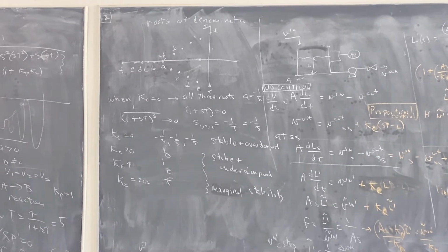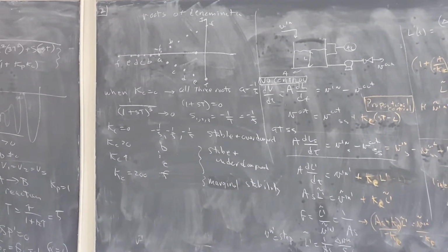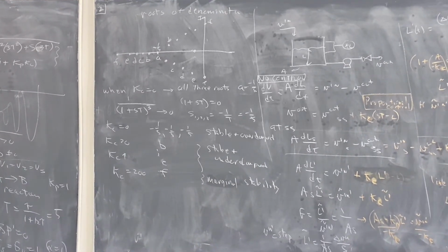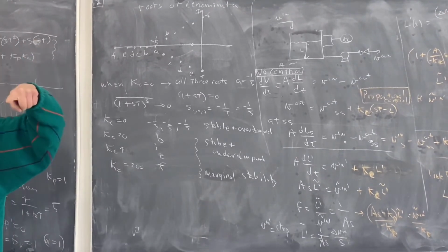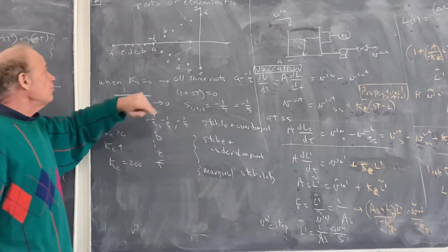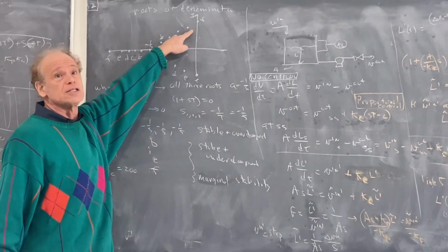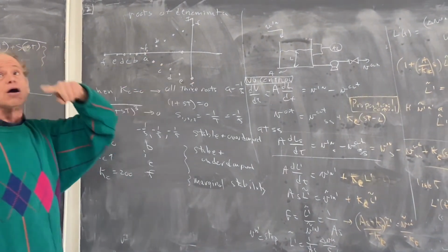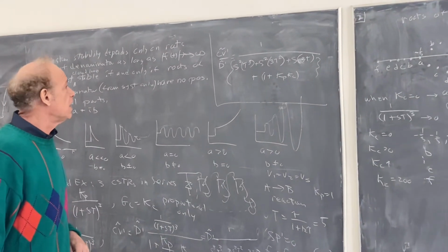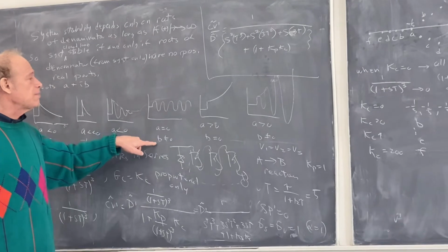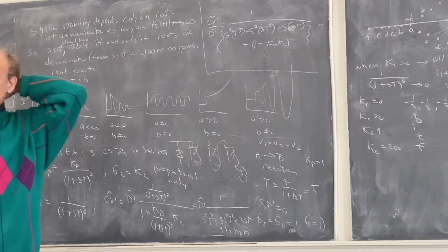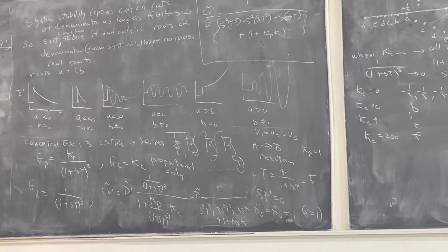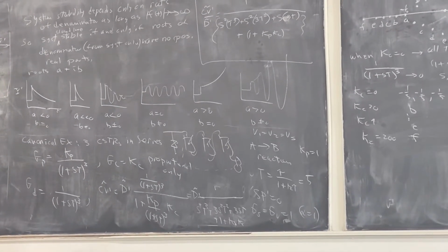When I do the inversion, each one of the 3 terms is multiplied by an exponential. And what we find here is one of the terms is going to decay exponentially. The other 2 terms are simply going to oscillate because they have real part 0 and imaginary part non-zero. So that's marginal stability in that the output doesn't grow, but it also doesn't shrink.